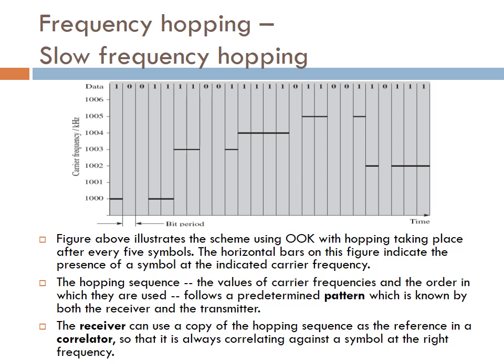When the mobile terminal is moving, the frequencies at which the fading happens keep changing, so it can't be predicted and avoided completely. By frequency hopping, the system ensures that the communication link is not trying to use the bad frequency all the time. Hopefully, the communication only hits a bad frequency occasionally. When it does hit a bad frequency, it might lose a burst of bits, but these can be corrected by error correction channel coding.